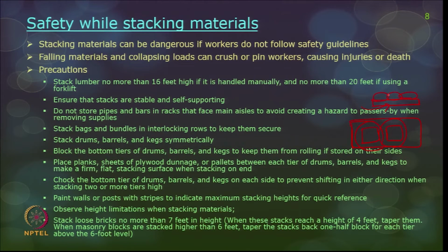And check the bottom tire of drums, barrels and kegs to prevent shifting in either direction, especially when you are storing 2 or more tires high. Paint walls or posts with stripes to indicate the maximum stacking limit, so that it is easy to identify for quick reference. You need not check the height each and every time. Observe height limitations when stacking materials, and put up posts or paint stripes so that the maximum stacking limit of a material is very visible.